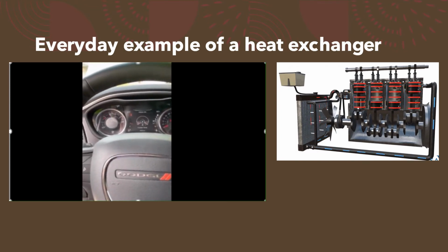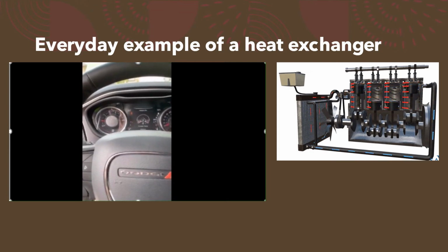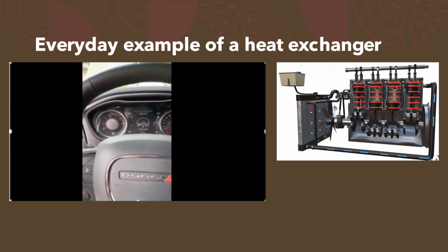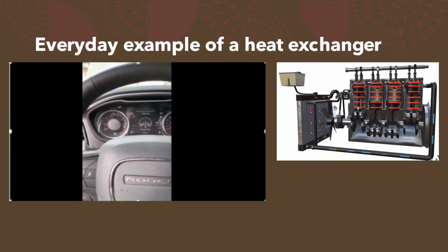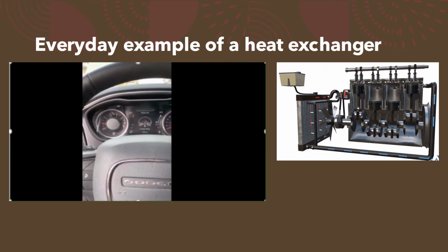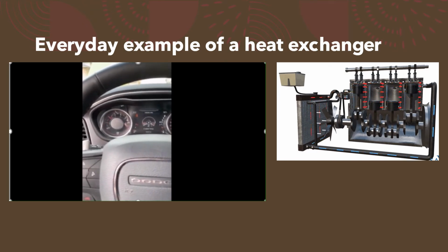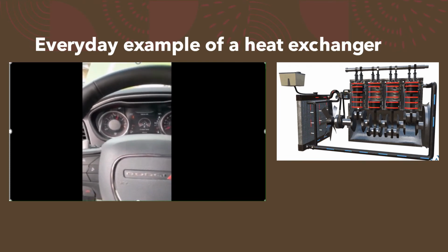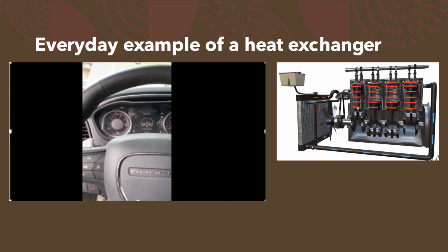will open, allowing the coolant to flow into the rad, which will enter through the top and flow down through the radiator. As the coolant is flowing down through the radiator, the cold air created by the movement of the car and the fan pulling in the cold air will cool the coolant down. As the heat transfer occurs, the coolant will then flow through the bottom of the rad at a cooler temperature and will return back into the system to repeat again.